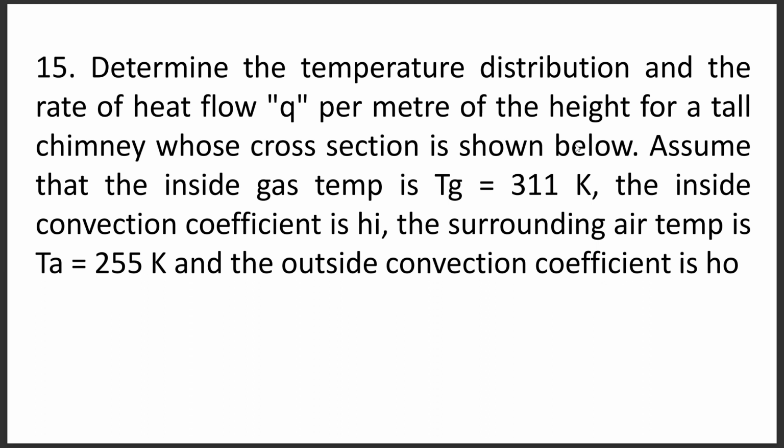In finite element analysis, meshing is very important because the better the mesh, the better the solution. If we want to achieve the convergence criteria, then we need to go for meshing and remeshing again and again. When the result is not varying, we can say that the convergence criteria is obtained.